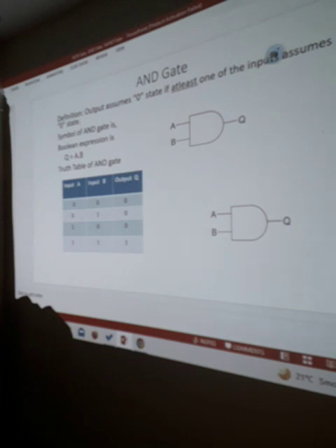Now this AND gate may be of more than two inputs, and the AND gate is made enabled when one state is given to one of its inputs, and if we apply pulses on the other input, then these pulses can pass through the gate because gate is open.